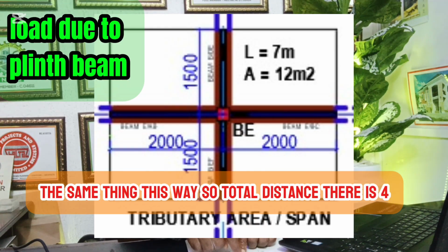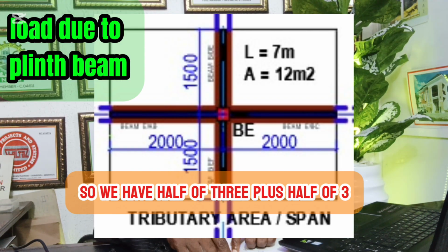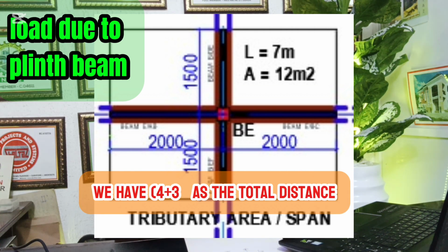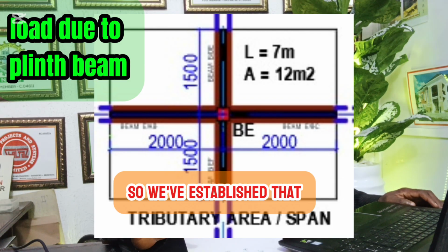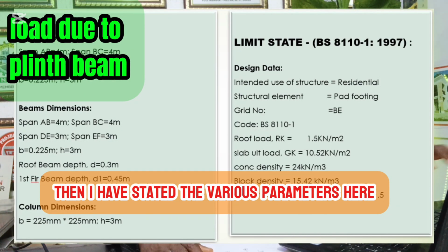So the total distance there is 4. The same thing on the vertical distance. So we have half of 3 plus half of 3, which is 3 also. So we have 4 plus 3 as the total distance that contributes load on this column. So we've established that. Then I have stated the various parameters here.